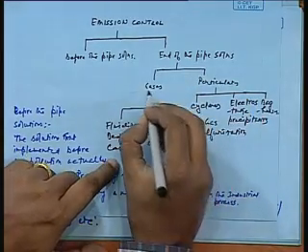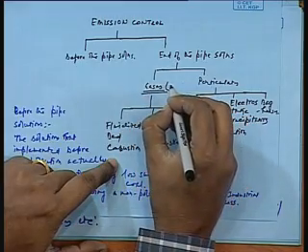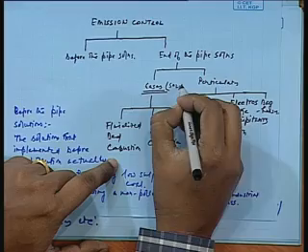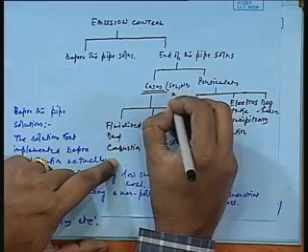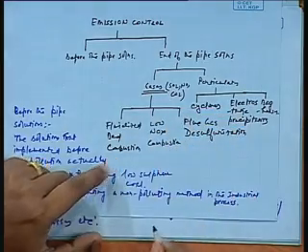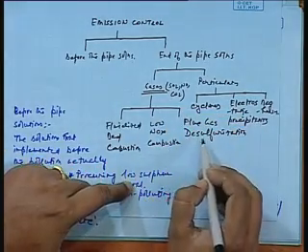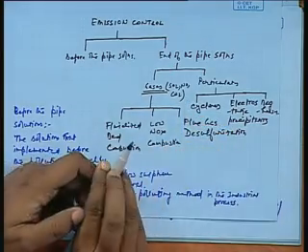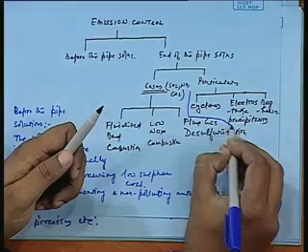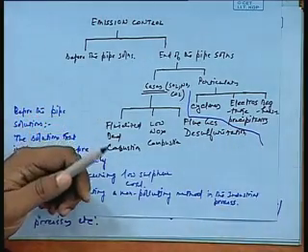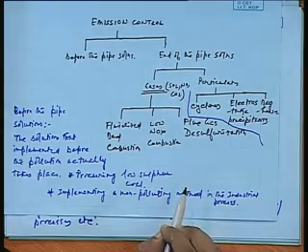That's gases. For the gases, the mostly concerned gases that we would be interested in are NOx. Then we would also be interested at one point in time in CO2. So, fluidized bed combustion, low NOx combustion, flue gas desulfurization. This is flue gas desulfurization. So, these are the three methods: flue gas desulfurization, or we generally call them scrubbers also.